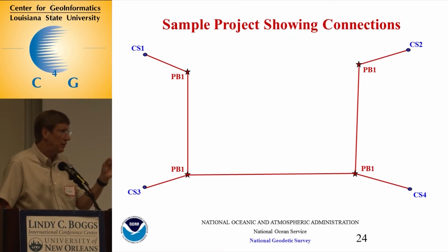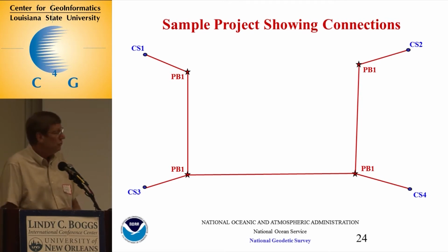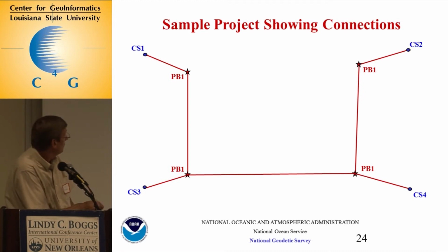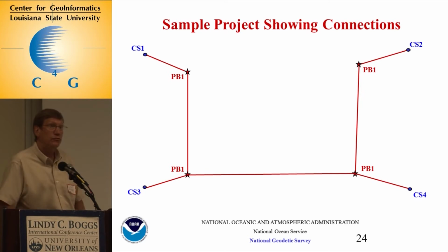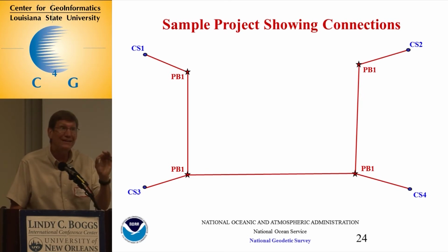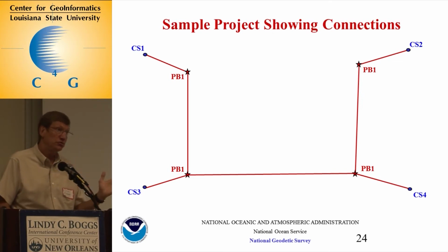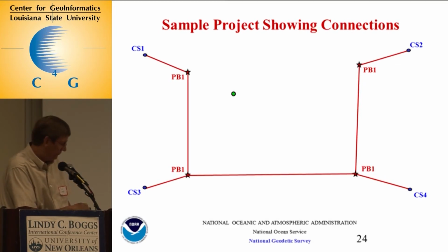Even though I may repeat myself. Remember, I showed you an example where I repeated myself, but I was off. So you're going to repeat these baselines 3 times. And if you can't check between here and here, then either that primary or the core information is bad, or inconsistent. It may be very accurate in truth, but you may be doing something that makes you inconsistent with the network, which is typically what happens when people can't get that check. But that's why we say the primary stations are like that.